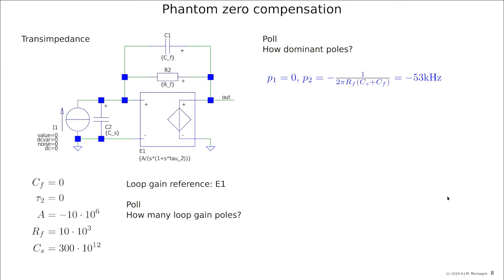And if you calculate it properly, we have a pole in the origin and a second pole at 53 kilohertz. And from the product of the loop gains and the poles, you can find the bandwidth, and that is what I was doing here: 410 kilohertz, which means both poles are within this bandwidth. There is no third pole, so they are both dominant poles. This can also be a question for the exam. So if you don't know this procedure, go back to the feedback model and the controller properties from the bachelor course.